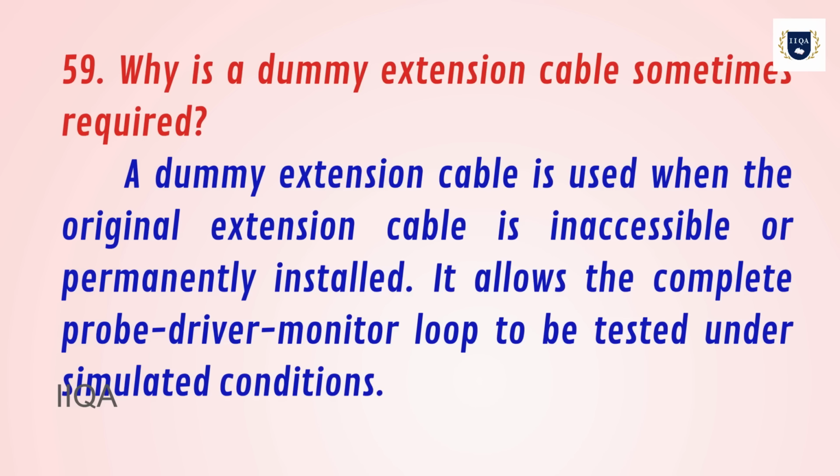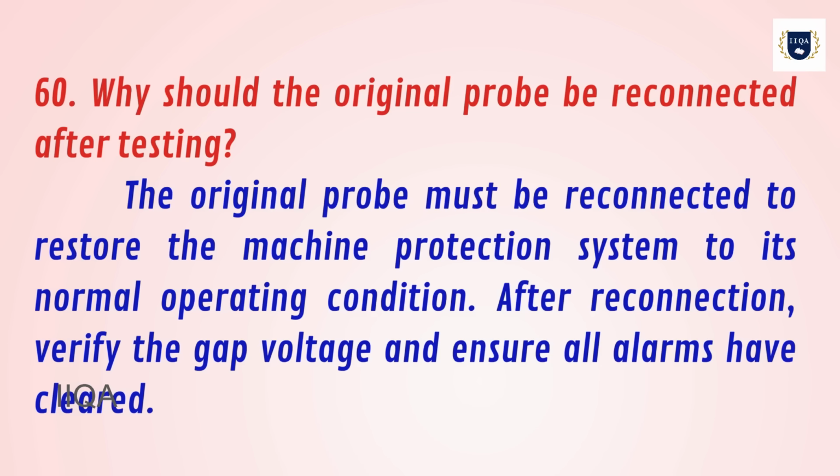59. Why is a dummy extension cable sometimes required? A dummy extension cable is used when the original extension cable is inaccessible or permanently installed. It allows the complete probe driver monitor loop to be tested under simulated conditions.